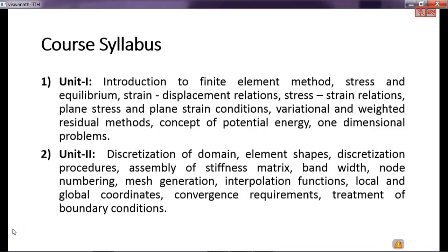So in the finite element method, if I take a bar, I can solve it as a one-element solution. I can cut it into two elements and solve a two-element solution. I can cut it into four, and solve 4, 8, 16, 32, 64, and so on. I can even make infinite chunks of elements. That means if I make infinite elements, the finite element solution should become the analytical solution.